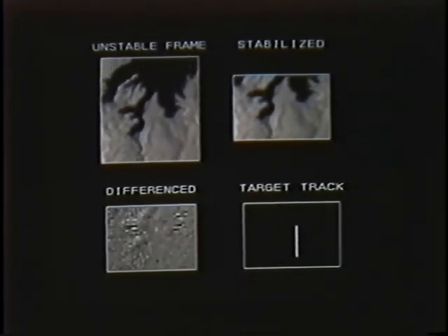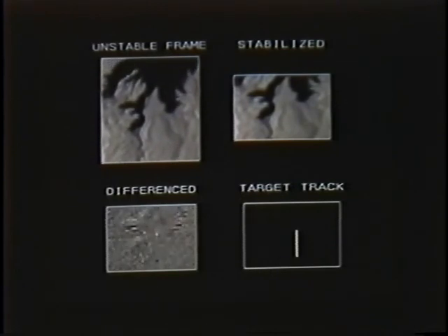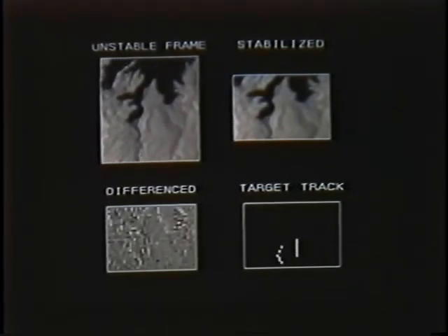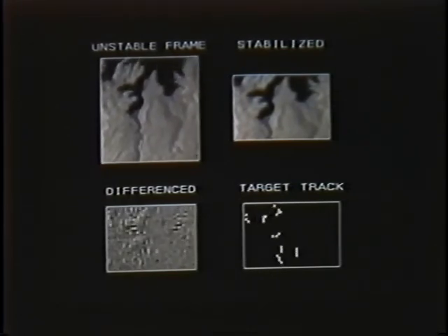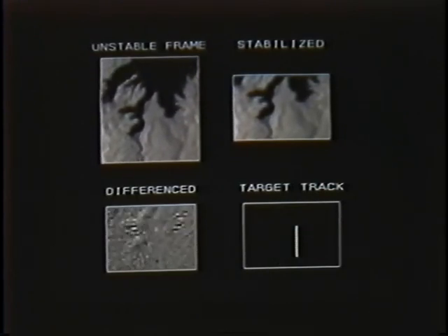By stabilizing the background, we, in effect, cause the background to stand still and make the target move. Now, with the combination of a stationary background and a moving target, we can successfully difference the frames and detect the target. Problems encountered in trying to detect targets in auto-track data is what originally prompted the idea of background stabilization.